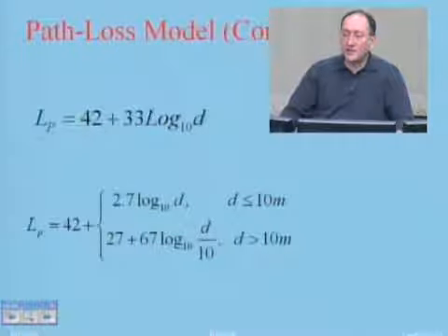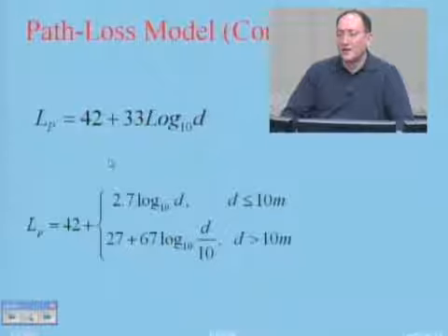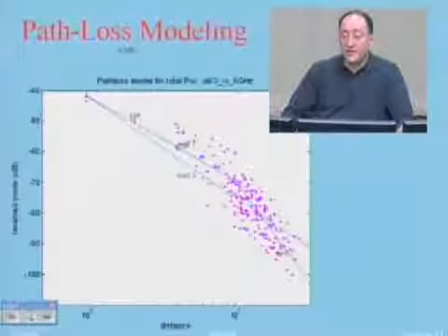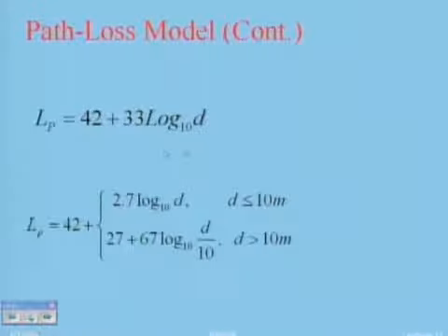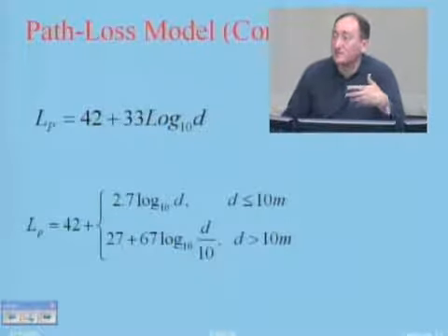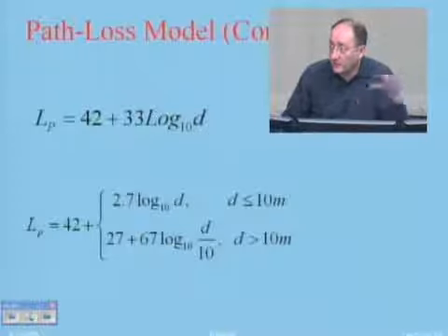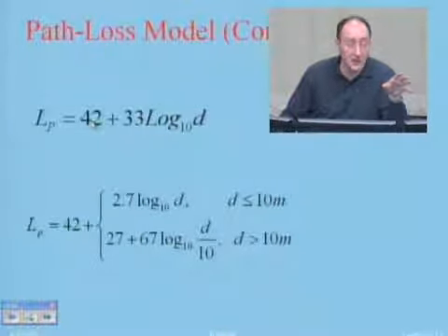This is a typical model that, I believe, my student Jin Rang Lee developed for one of our projects. Basically, if you take just one line, the path loss model would be like this. 3 gigahertz to 6 gigahertz, the center frequency is 4.5. If you put it in the equations for calculation of path loss at 1 meter, you get 42 dB.